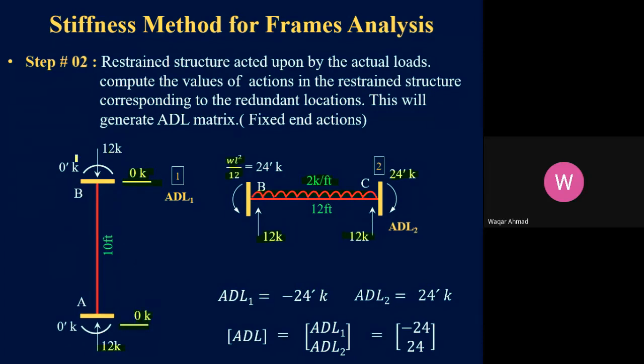And what about the moments? Now there is no moment possible here. Why is there no moment here? Because we don't have any load acting on this member, which causes a fixed end moment.